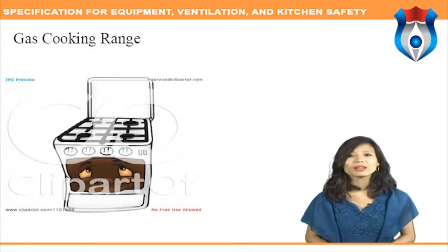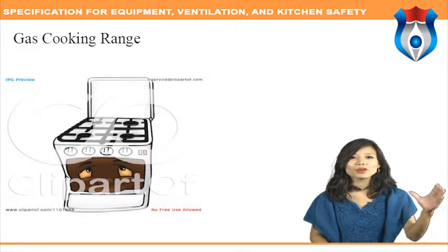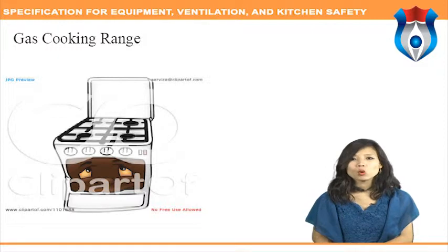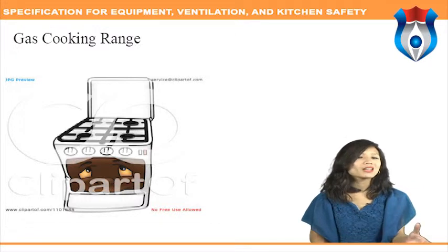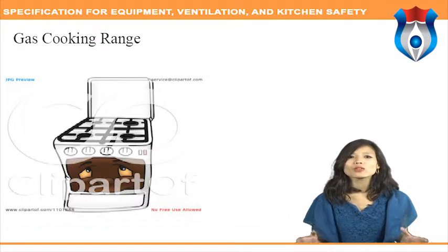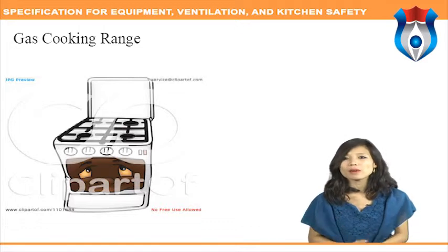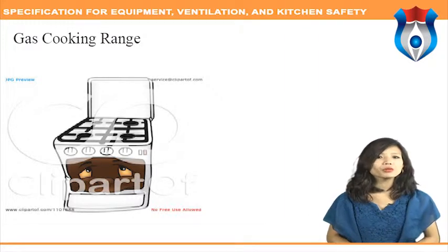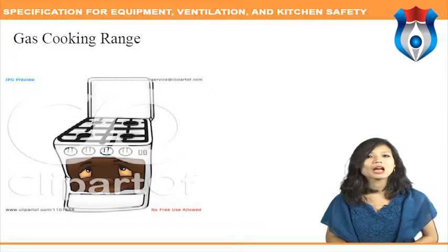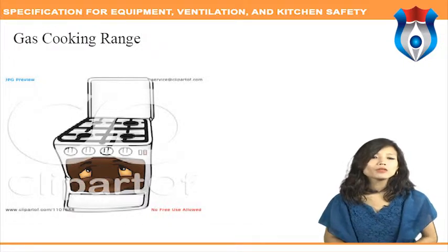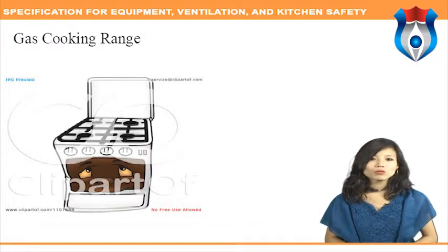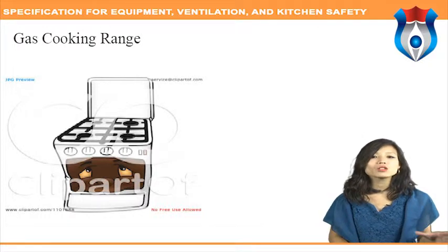Gas cooking range. Gas cooking ranges have open top burners with high pressure burners T22, T35. They are tailor-made for the client's requirement. They are manufactured in different combinations such as 2-in-1, 3-in-1, 4-in-1 and 6-in-1. The length and breadth of the range depends on the quantity of food to be prepared. In case of a la carte preparation, a combination of high and low pressure burners is used, the area being 14 into 40. The height of the cooking range is 33 to 34, but for ideal bulk cooking, the length varies from 20 to 34 per range and the height is reduced to 18 to 20.